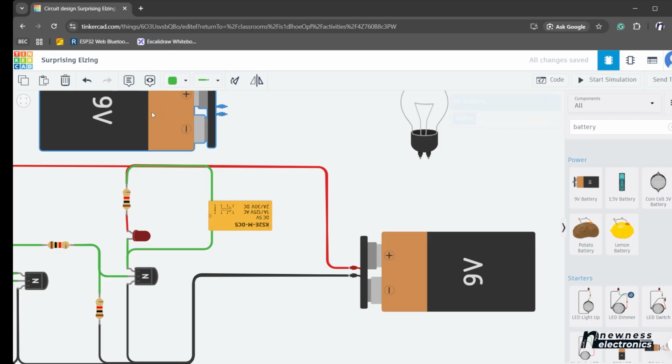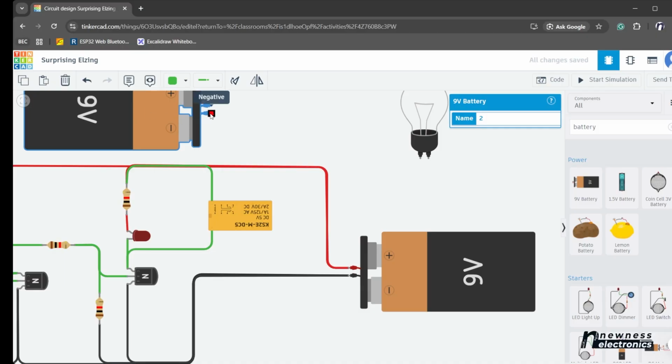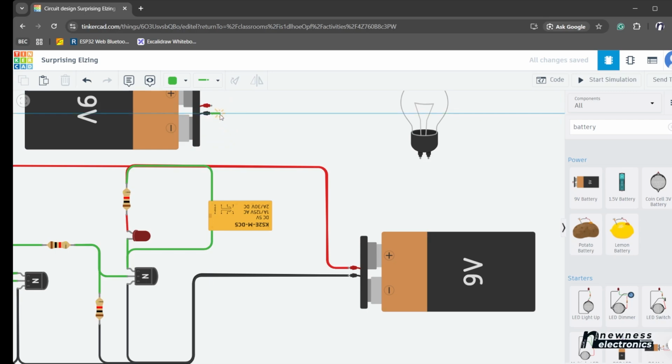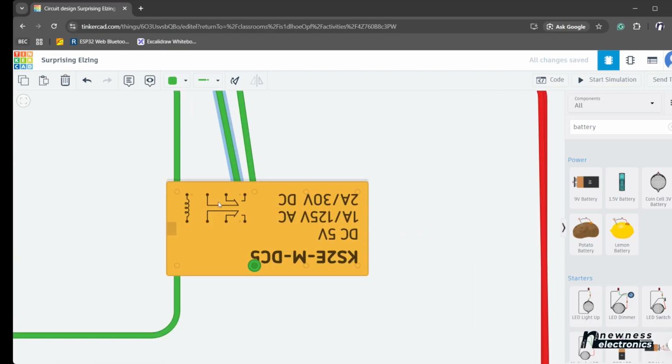So in connecting, we connect the negative, the neutral, the neutral now. You should connect both of them to the common of the relay. That is, for this relay, this is the common here and here, according to the diagram. Do you get? According to the diagram, these places are the common. So here and here.